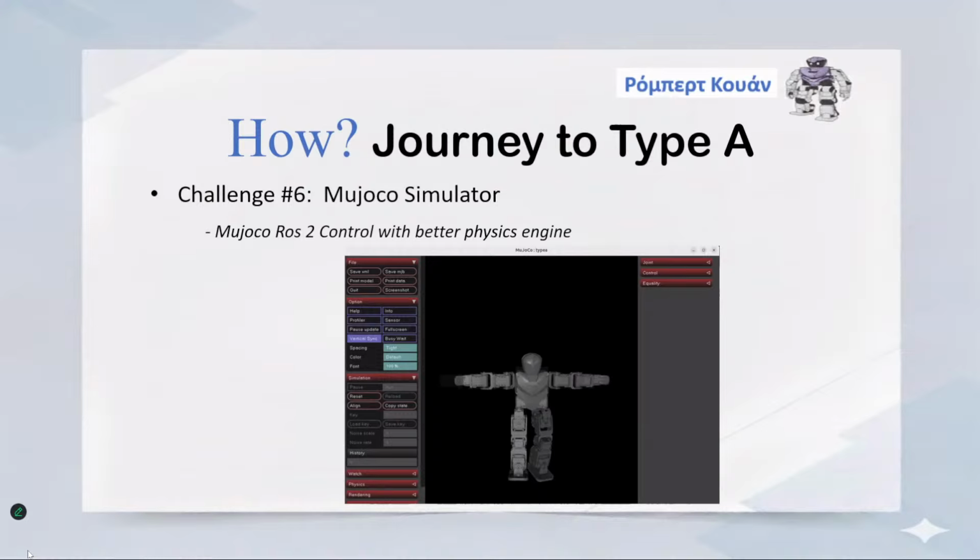But the problem I encountered at the beginning is mainly the conversion from the URDF file to the XML file format for the modeling. I couldn't find any good conversion tool, so I had to do a lot of manual checking, trial and error, to configure how the XML format should be, and got to this point finally.